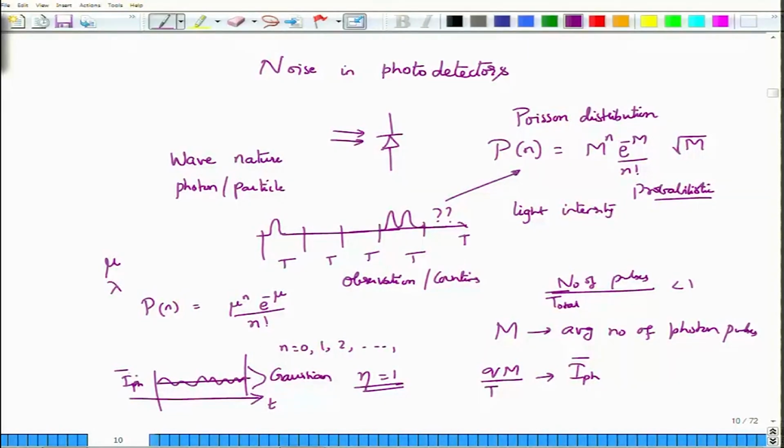Now, average photon current increasing means that the optical power you have launched also increases, which means the m value increases. But please remember that although we are assuming a continuous behavior here, inherently this is of a discrete nature. Inherently, photons are not emitted in a continuous stream. They are emitted with this probabilistic scheme, only the uncertainty reduces as the average photon number increases.